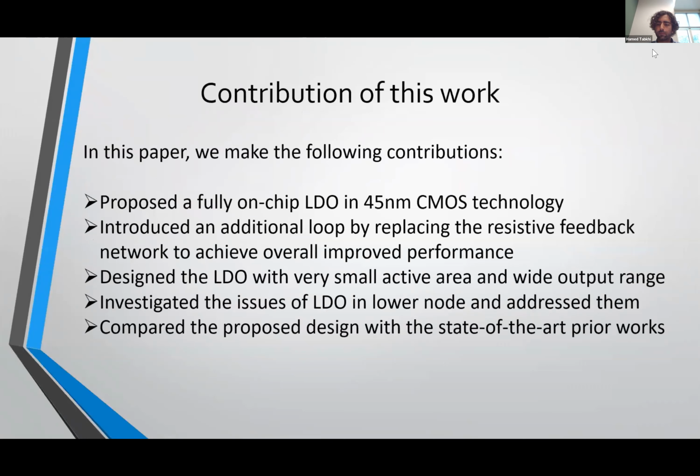So in this paper, we make the following contributions. Proposed a fully on-chip LDO in 45 nanometer technology, where no external capacitor is needed. We introduced an additional loop by replacing the resistive feedback network to get the overall improved performance, like the transient performance, we're trying to achieve good transient performance as well as the PSRR. Designed the LDO with a very small active area and wide output range. And we investigated the issues of LDO in lower nodes and addressed them, because there are very few designs currently available in 45 nanometer. And at the end, we are comparing the proposed design with the state of the art prior works.